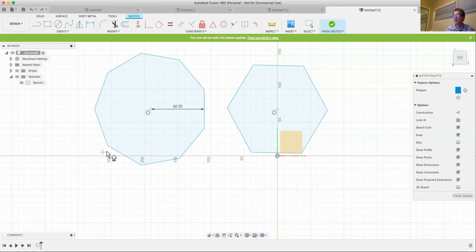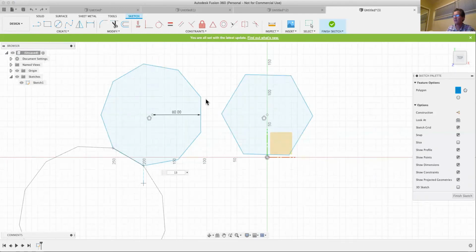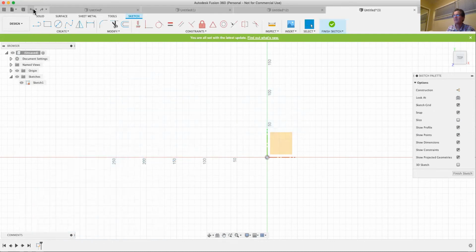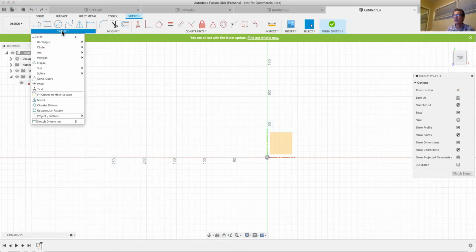And then the edge polygon. Basically, maybe you want to use something that's already there. You define an edge, and then put my polygon over here. In this case, I want to have 13 sides to my polygon, and there I go. And just define which side it's on this way. Okay, and I'm just going to back out a couple of these so that my palette doesn't get too crowded here.